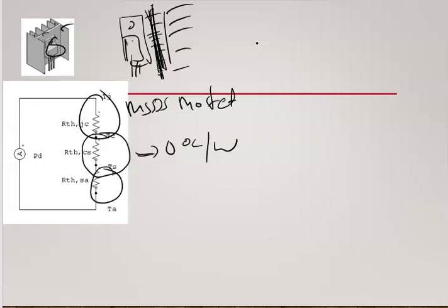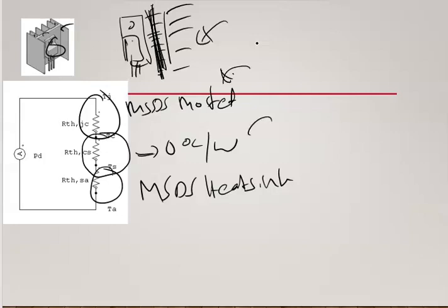Meanwhile, the heatsink itself is provided by the datasheet of the heatsink manufacturer. So each of your products or materials here, the characteristic is provided by their own individual manufacturer. But if the device is directly and firmly sealed or soldered to the body of your MOSFET, between MOSFET and heatsink, the resistance is considered as 0.